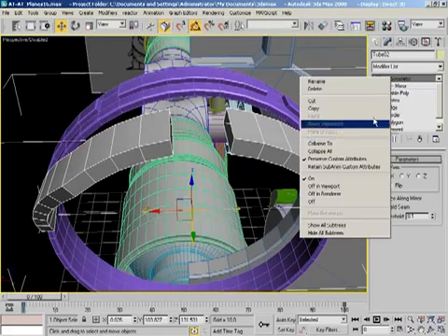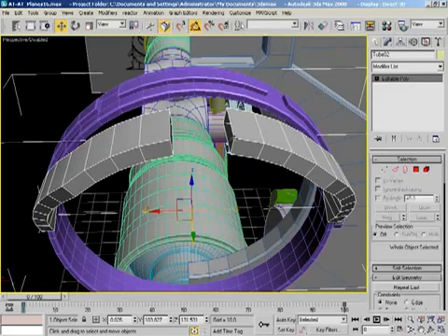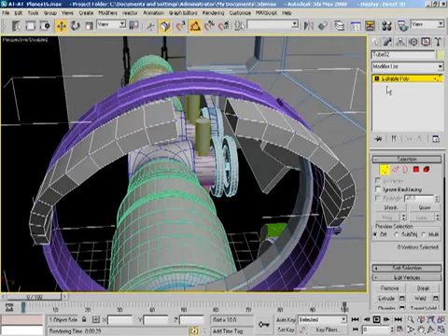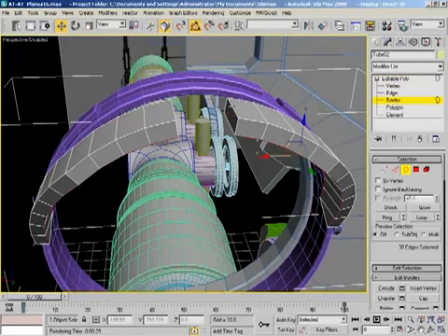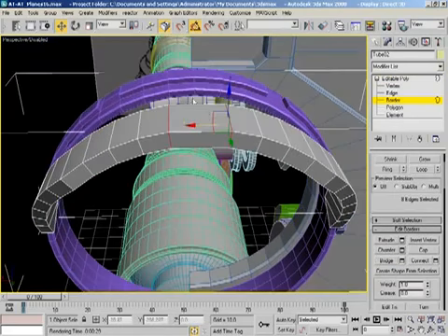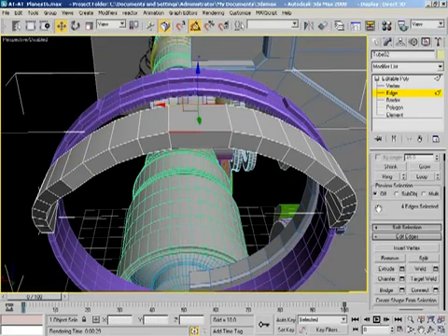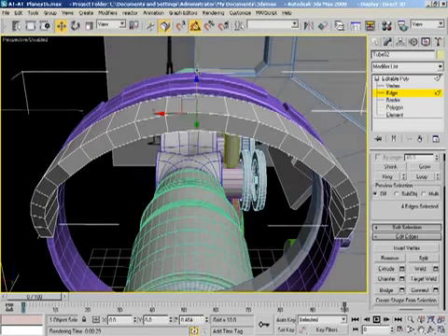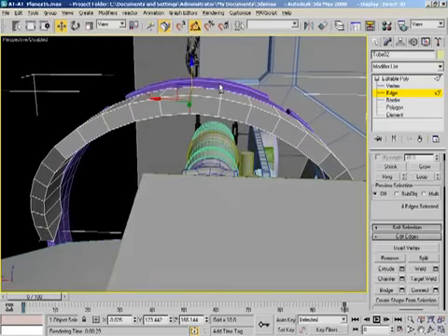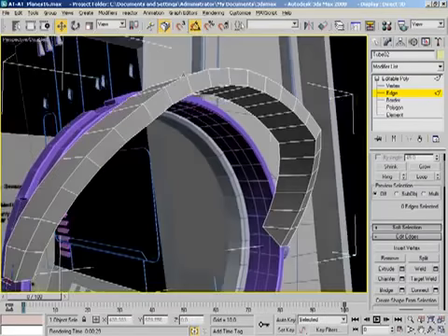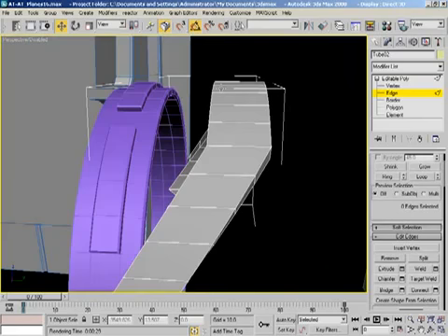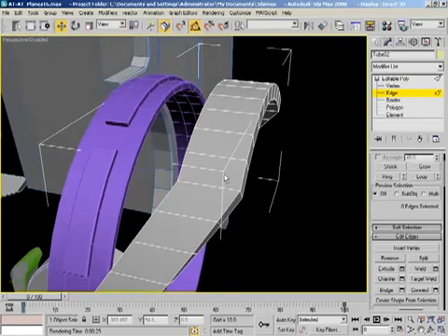First, let's convert this all back over to an editable poly. Now let's grab our borders. Grab this border and this border, and let's just bridge those. Let's grab edges, and let's ring those. Let's connect those. Click OK, grab that new selection of edges and tug them up slightly, and then we've pretty much rounded that back out. I mean, it's probably not exactly accurate, but I'm sure it'll do the job.